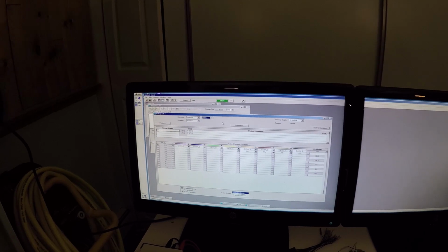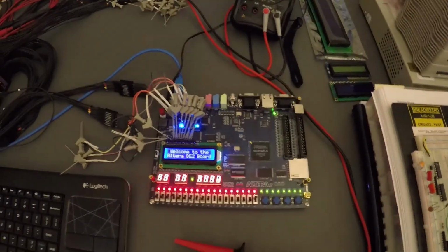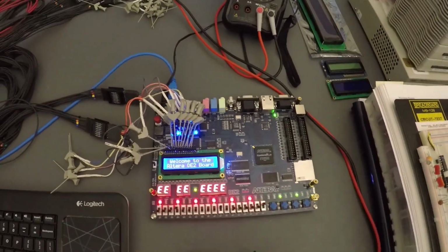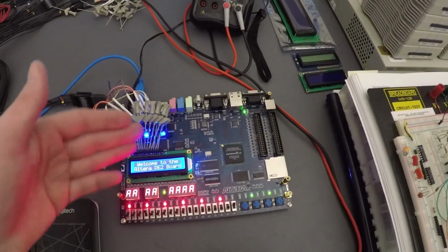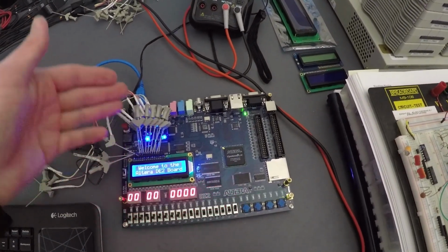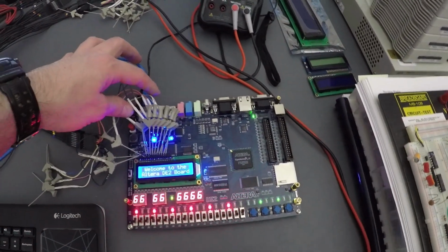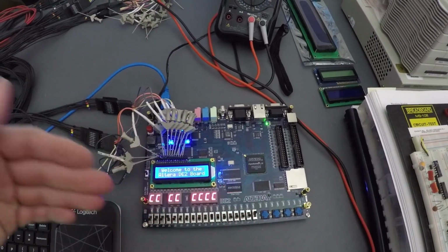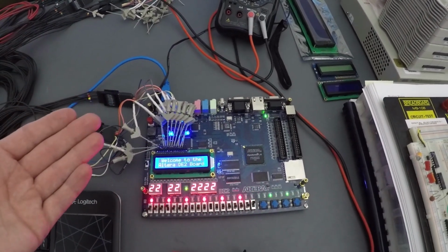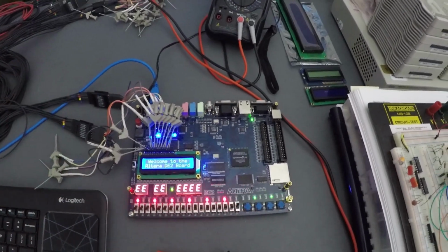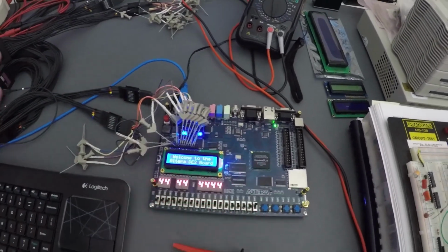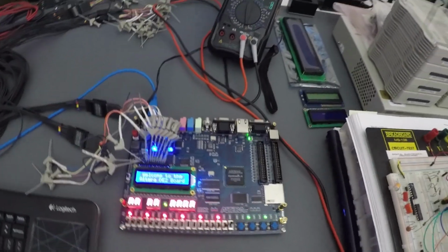And so now I'm going to activate the power on our Altera DE2 board, and so there you have the standard welcome message. And right now it's going to be monitoring the databus, our 8 bits, and once it detects a hex value on that databus of 38, it will proceed through and capture and then display it on the screen for us.